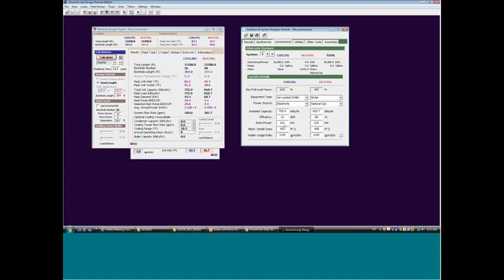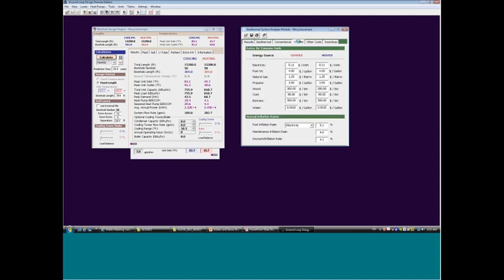Once we do all this, we get some numbers that come up here. So the cooling power is predicted to be about 37,000 kilowatt hours for the year. No water again. And then other, it's going to use about 4,500 therms per year from the boiler. So it does all these calculations for us. And then we go to the Utilities tab, and we can enter our utility rates for the project or location.